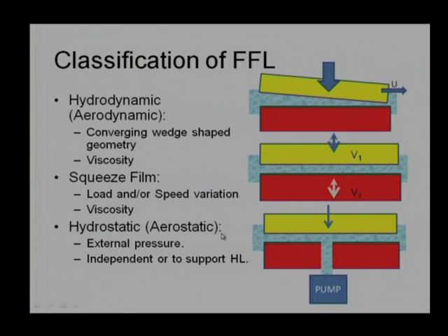Last one is the hydrostatic. You see that we are supplying liquid with pressure. So, there is a pump which needs to supply pressure to levitate this yellow block. Yellow block is carrying the load, right. As I mentioned, it will be a costly affair because using a pump to lubricate requires energy. There will be consumption of energy as well as initial cost of the pump and maintenance cost of the pump. That is why it is least preferred compared to squeeze film action, compared to the hydrodynamic action.